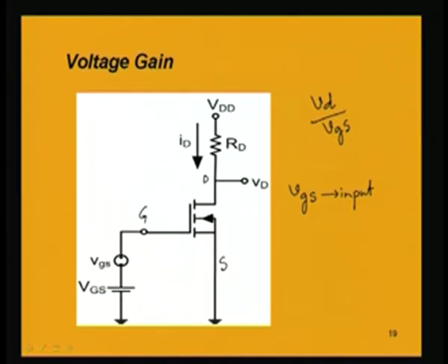When we write the voltage equation, we write the instantaneous voltage equation, that is small v capital D, because apart from the AC signal, we also have DC voltages, which are required for biasing the MOSFET properly, because we know that it is an N channel enhancement type MOSFET device.